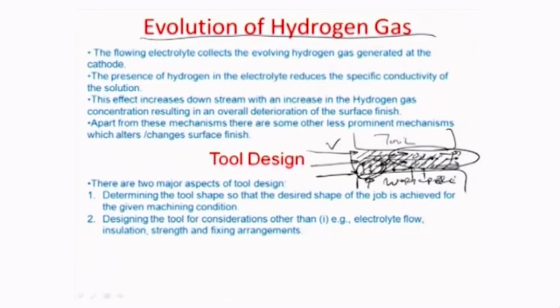There is a density gradient which is created for the gas which is dissolved, and therefore, the conductivity is varied across the length of the workpiece even, and because of that again there is a tendency of the conductivity to vary and also simultaneously the current density to vary. So, at one point where the current density may be more because of reduced hydrogen, there may be a slightly greater dissolution rate in comparison to the point where the current density is lower. Okay. And therefore, again this can also result in some kind of roughness, where some points may be moved or dissolved at a greater pace in comparison to the other points.